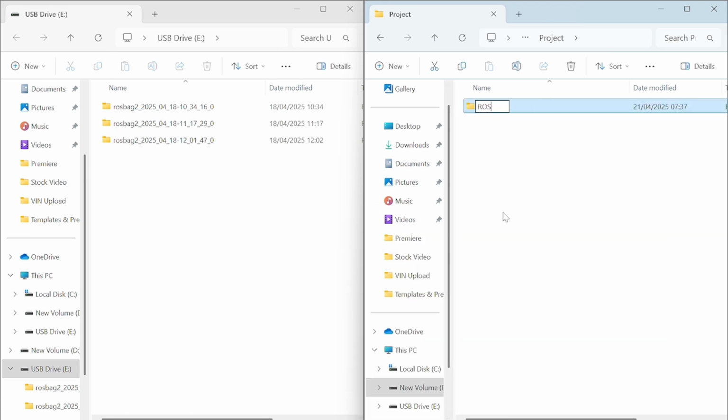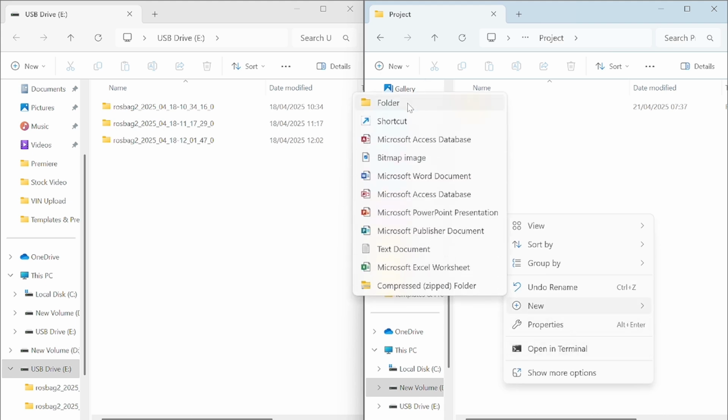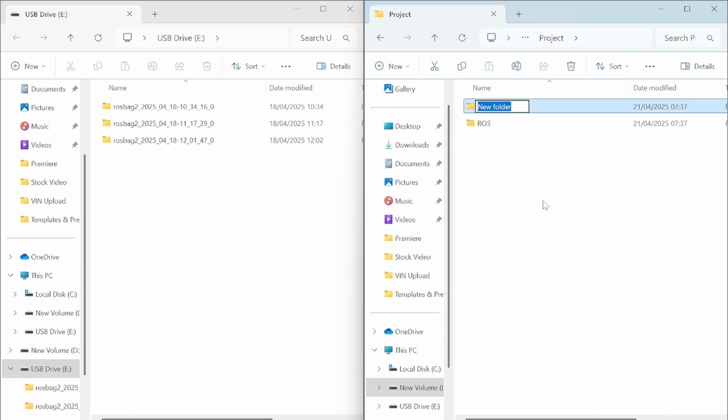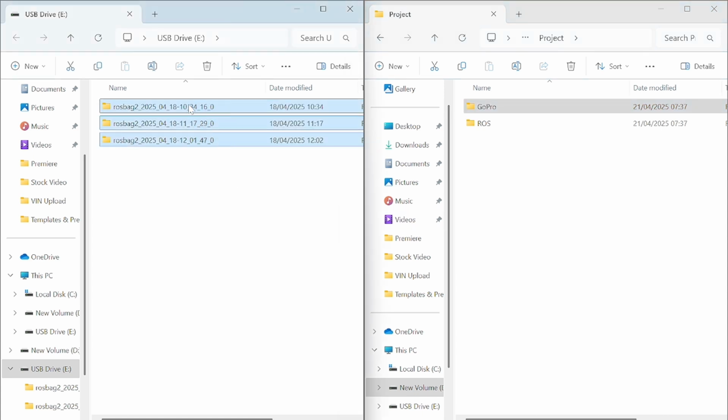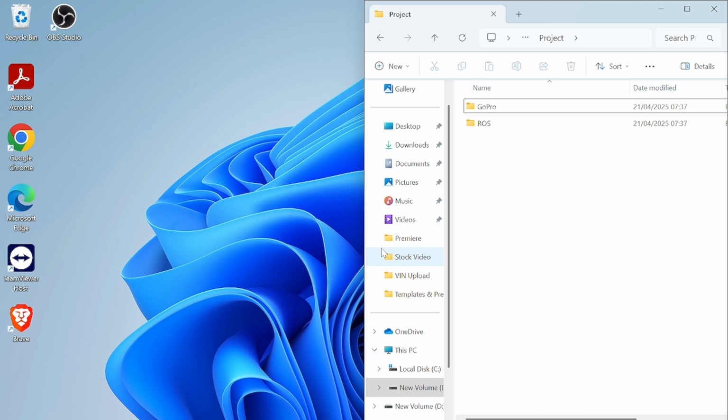The files that you will need to upload are ROS files from a USB that contains LiDAR files, and GoPro files that contain visual inspection data, blade ID, and route photos. Now, copy all image and video files from the SD card into the corresponding turbine folder. These serve as your backup in case of any issues later.